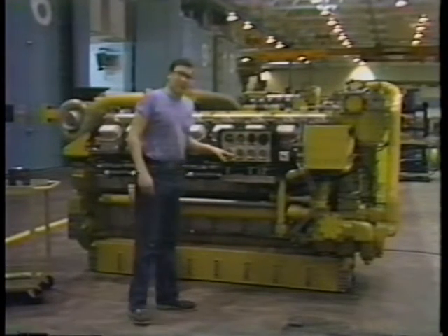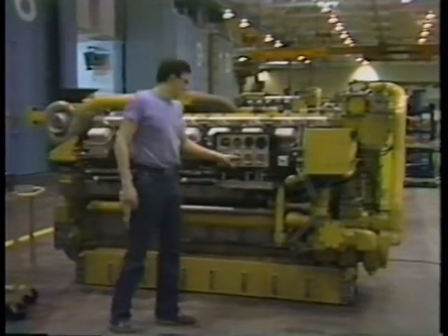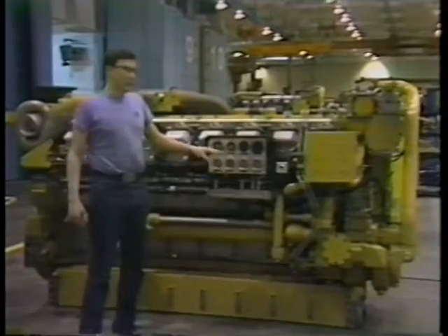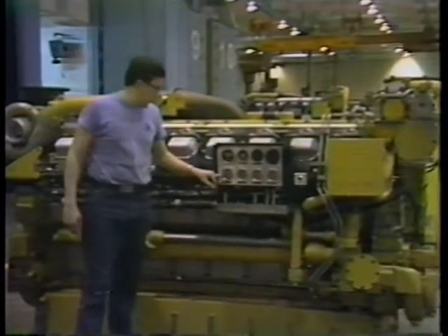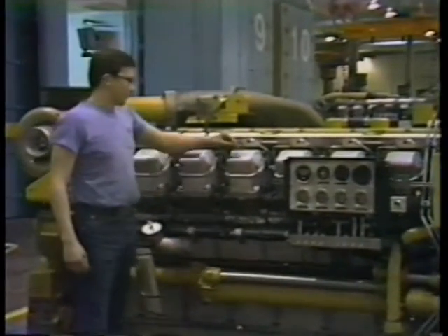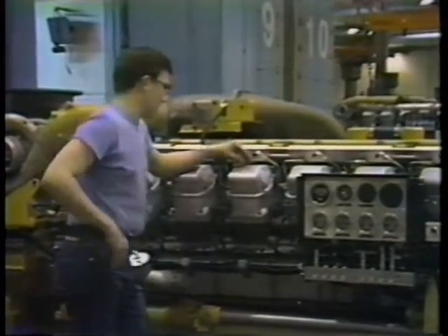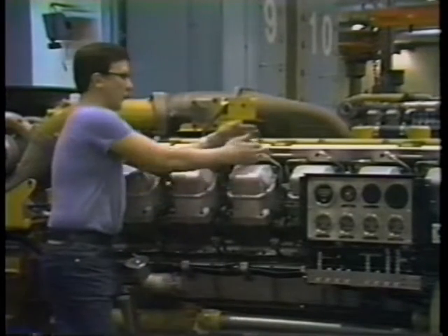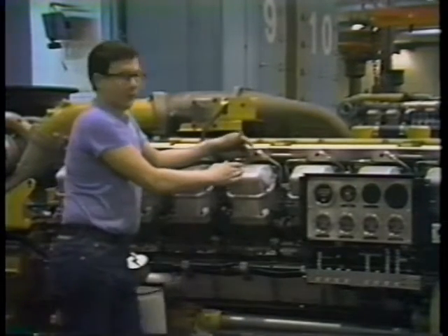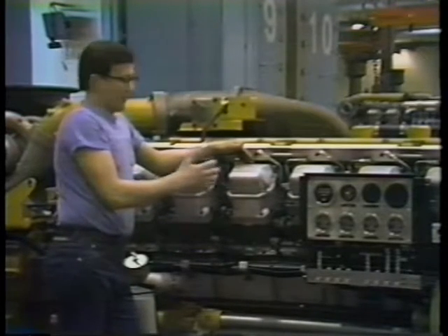These gauges tell the conditions of the different fluid power components we have on this engine. One is fuel pressure, jacket water temperature, jacket cooling water. We have engine oil pressure that lubricates the engine. Right here, under this valve cover, is where the power for this engine starts. We have fuel coming in these manifolds to a unit injector. As the piston comes up, this is how we get our power.